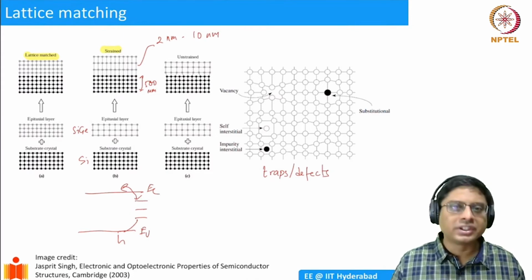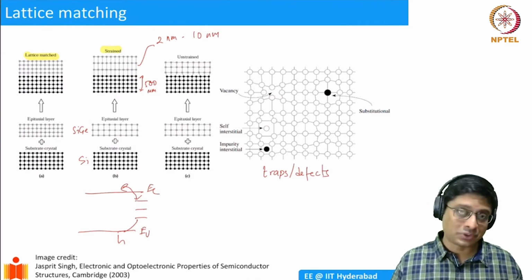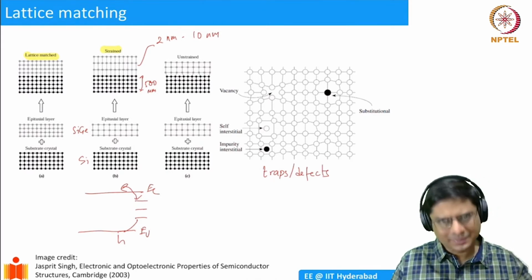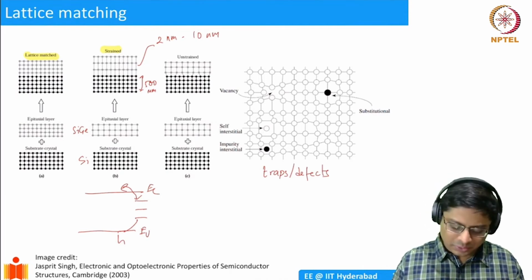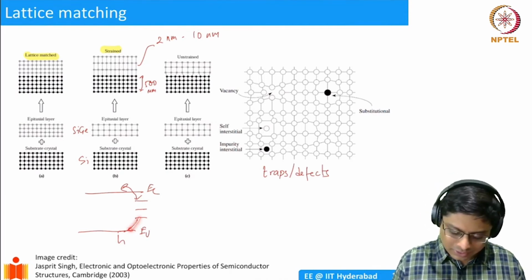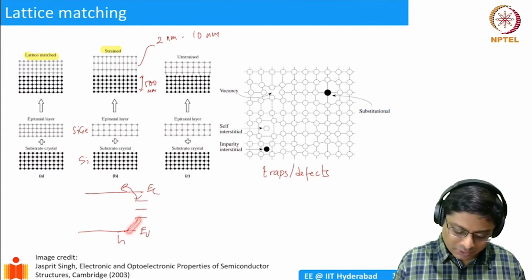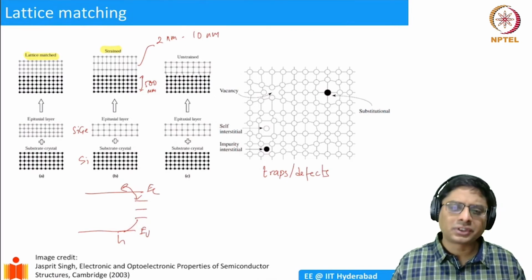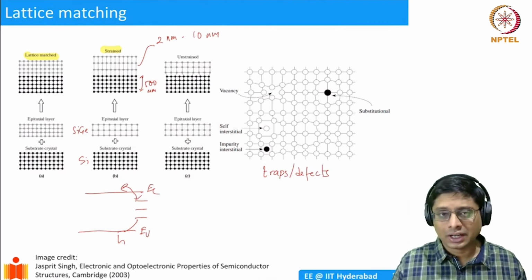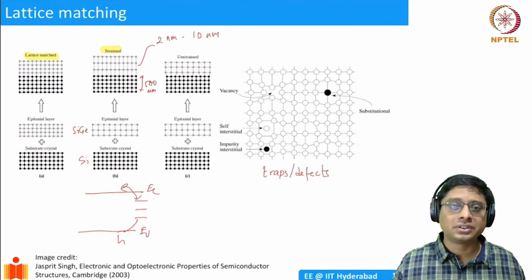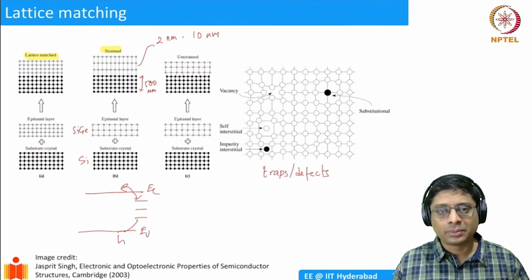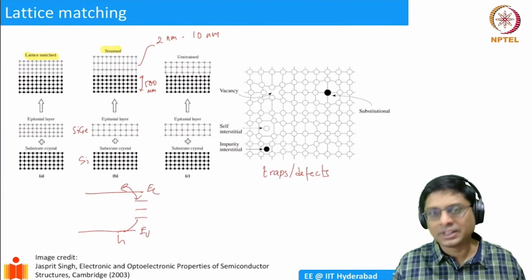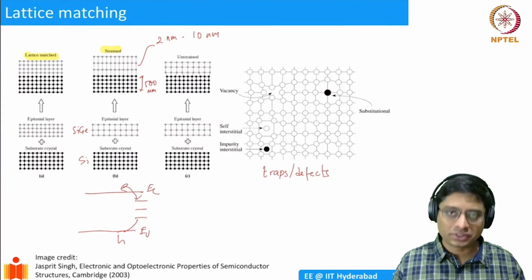You already saw that recombination is inversely proportional to the difference in the energy. If your energy difference is large, then the recombination probability is small. Okay, same as generation, just the inverse process. But now if you introduce a trap level, you are actually having a higher probability of this transition happening, higher probability of this transition happening. So the overall probability will increase. Okay. So this is a second order process, but it is significant enough for us. And in optoelectronic devices, it's absolutely undesirable, because whenever an electron recombines through this process, it does not emit radiation that we like. Right? Maybe it is just emitting as heat, or it's emitting at a different wavelength, which we still don't like. Okay.